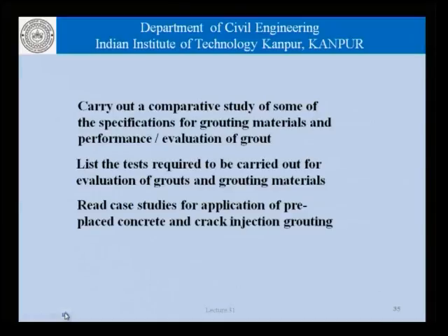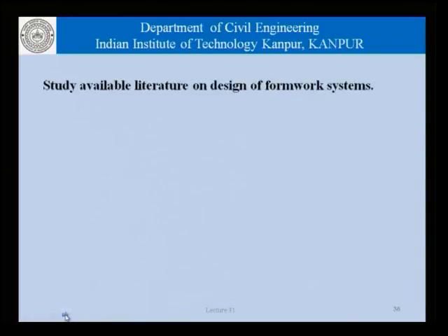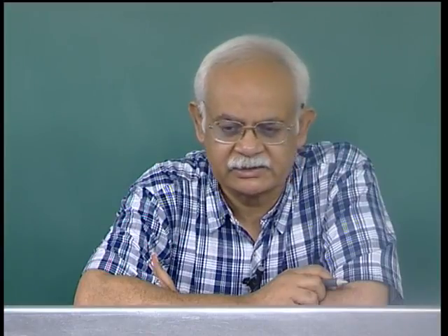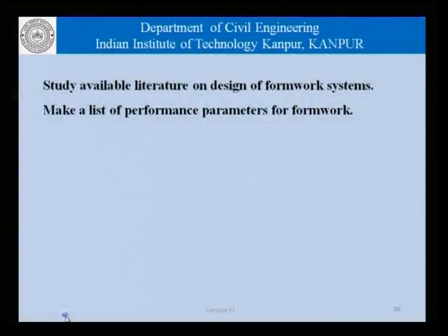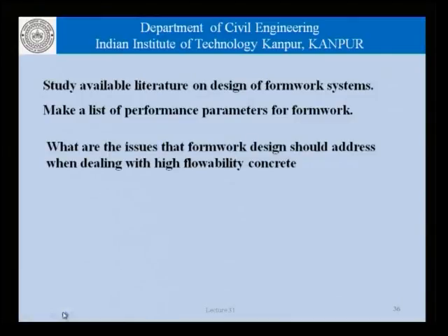We could talk in terms of reading case studies for application of pre-placed aggregate concrete and crack injection grouting that we saw briefly today. On the issue of formworks, I would request you to study available literature on the design of formwork systems. Very often the durability of concrete structures is compromised because the temporary formwork system is not appropriately designed. We could make a list of performance parameters for the formwork systems and list what are the issues that formwork design should address when dealing with high flowability concretes, which is becoming more and more increasingly used in concrete construction.